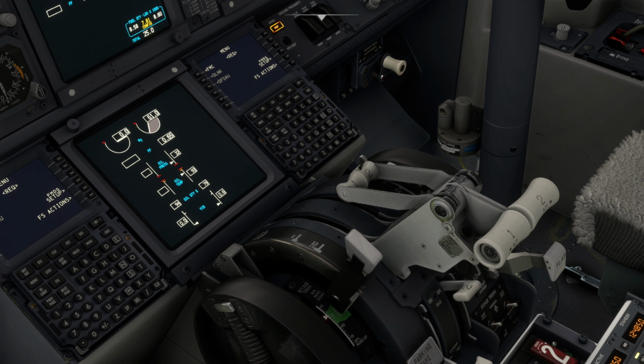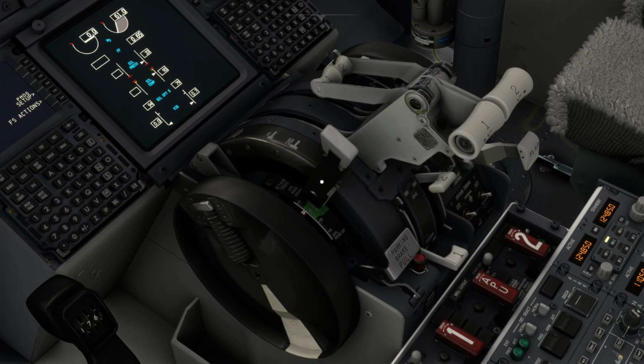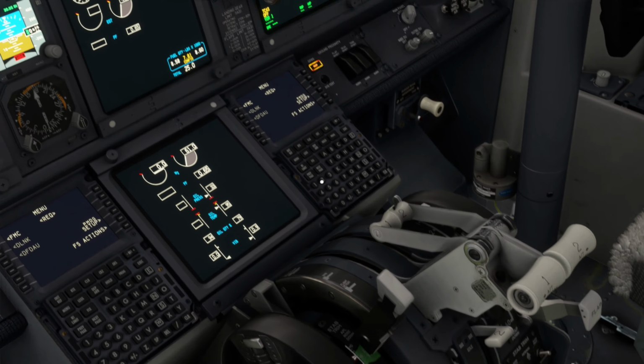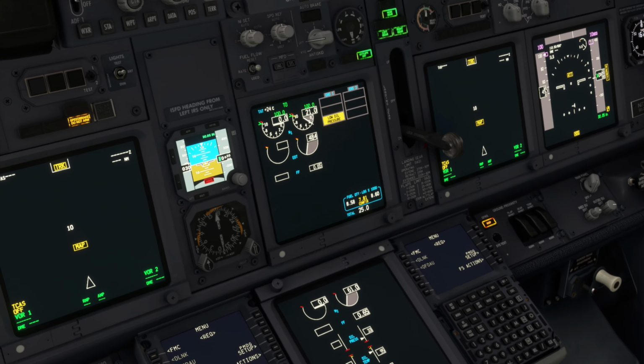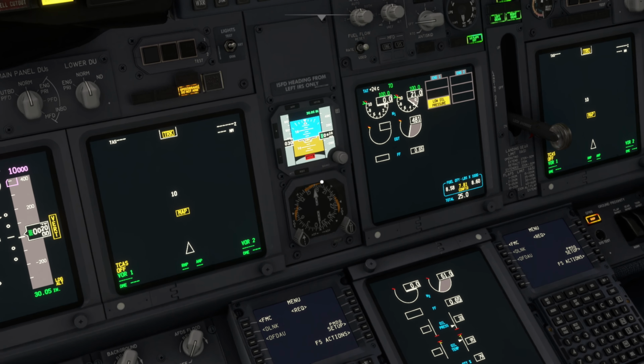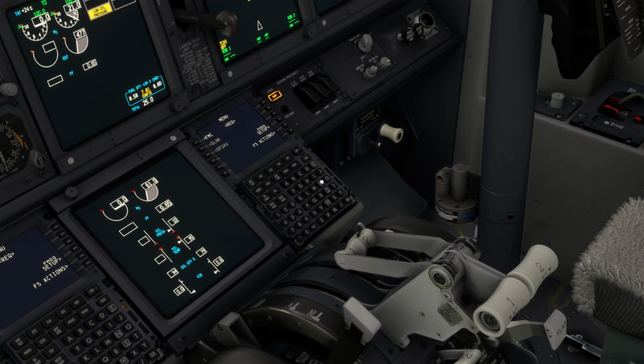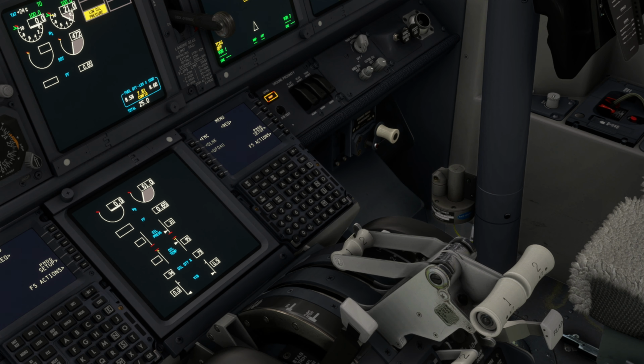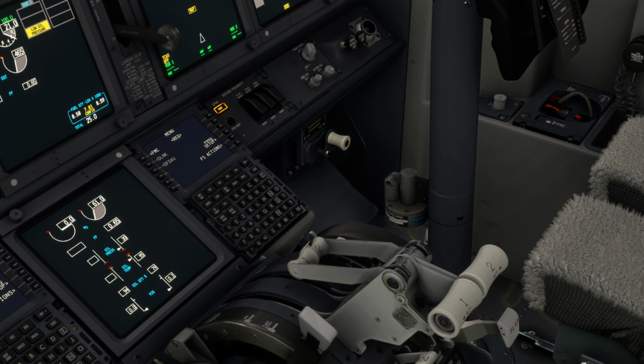We do not see that symmetrically. We see that on the right-hand engine, engine number 2. We do not see that on engine number 1 on the left-hand side of the aircraft, which tells me that we may have had a complete hydraulic failure, either because of partial hydraulic pressure existing, allowing for the thrust reverser deployment on engine number 2 prior to the complete loss of pressure, or the aerodynamic effects on the potentially failed engine number 2 have opened up the thrust reverser duct on engine number 2. We don't really know at this point.